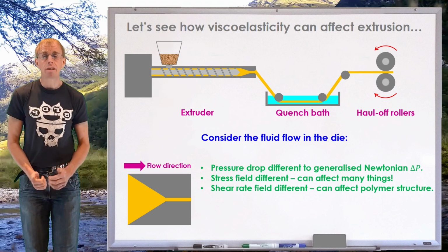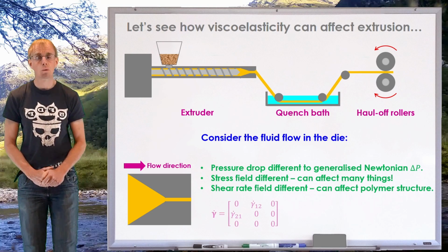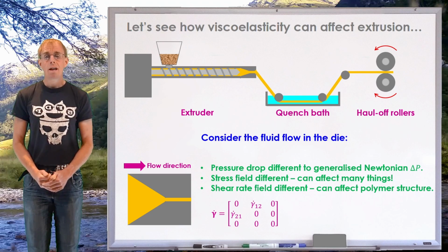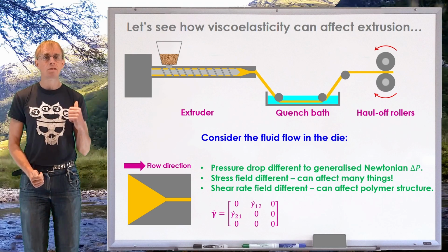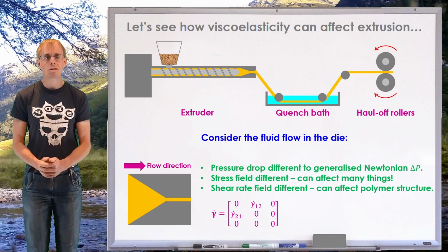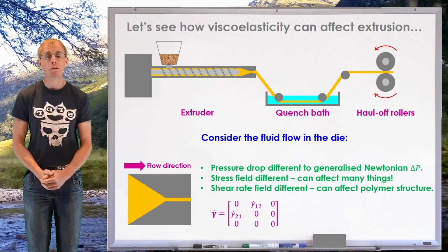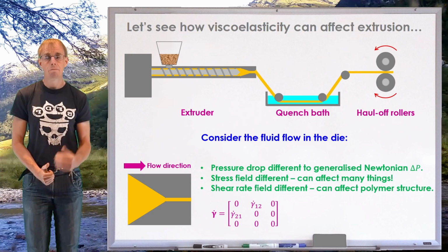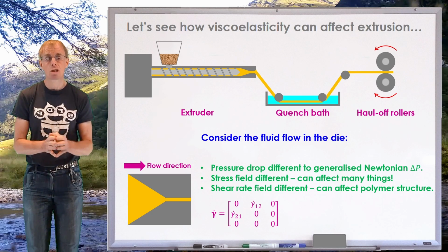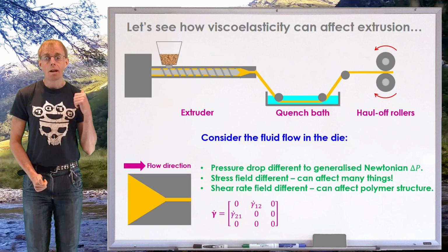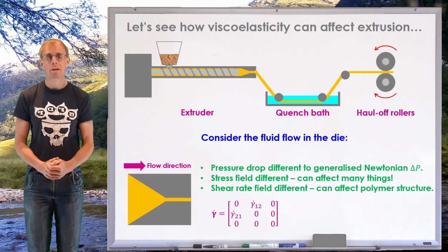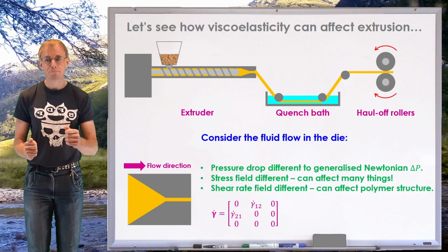Now, the reason underlying this, of course, and hopefully you'll recall this, if not, don't worry, we're going to be talking about it more next lesson, is if we think about, say, a simple shear operation. Let's say all we have is a pipe flow with a shear stress. The shear rate tensor might look a little like so. You've just got that shear rate in the 1-2 position there. And of course these tensors are symmetric, and so you see it twice.